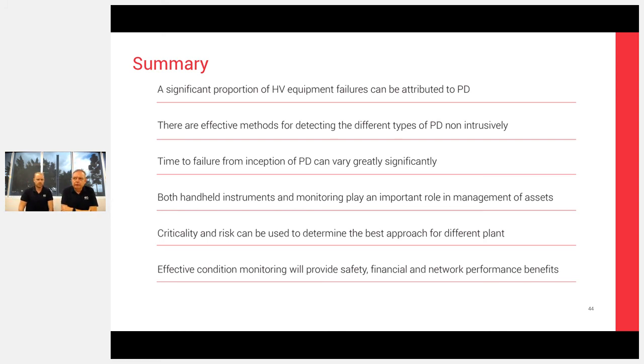So for transient earth voltages, TEV tends to travel across the surface. The sparks, due to the skin effect, will travel quite readily across the surface of the metalwork. So we typically only put 1 TEV sensor on each cubicle, or every other cubicle if we're trying to reduce cost and have very large switchboards.